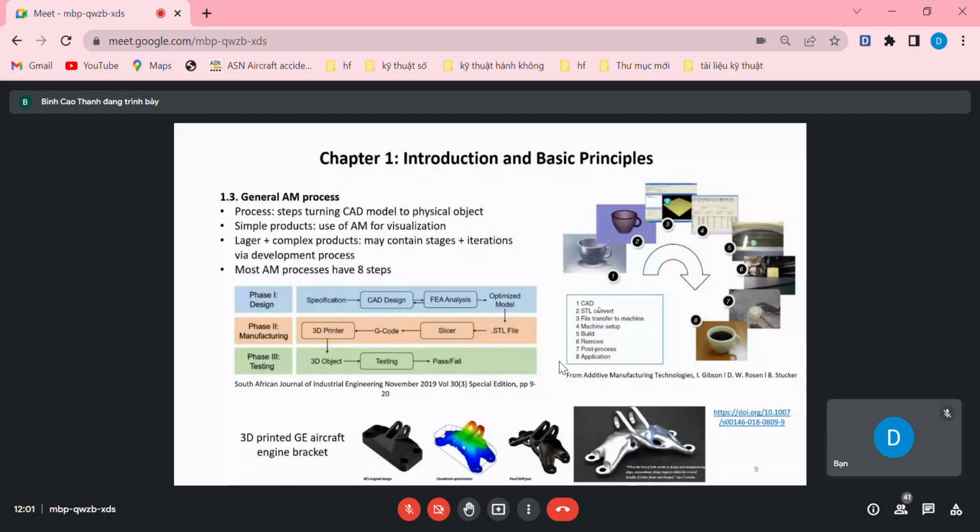We are using Inventor, let's say. You can use reverse engineering, like computational tomography, in order to scan layer by layer. So you have the point cloud, and then you use the appropriate software in order to reconstruct the cloud into a model, and you use the model as the normal CAD model that you construct by using, let's say, SolidWorks, for example.